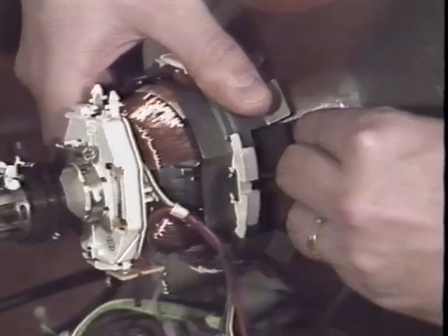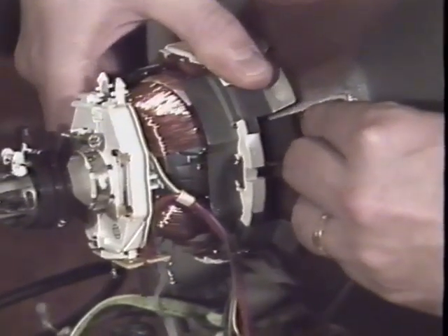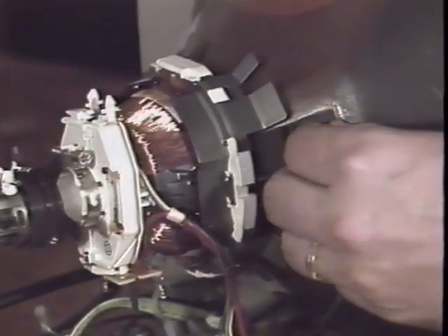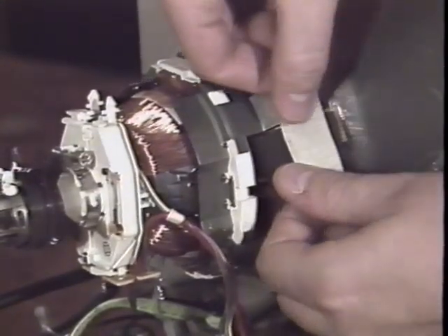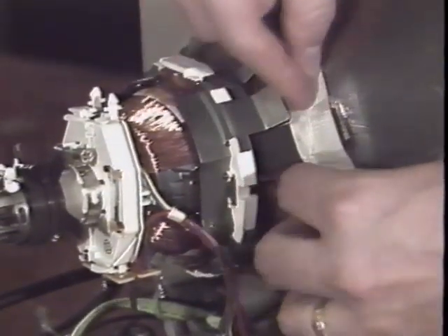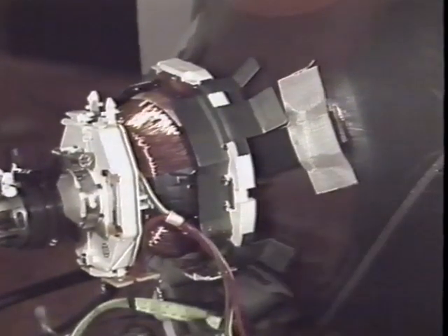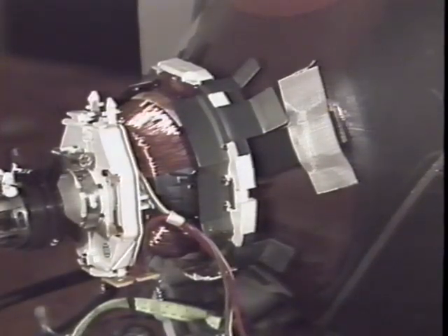When the edges of the display are as close to pure white as possible, insert the final top wedge to secure the yoke. You may need to change the position or depth at which the wedges are inserted to obtain the best convergence. This is the last of the magnetic color adjustments. Recheck the purity and raster tilt adjustments if necessary before moving on to the electrical alignments.